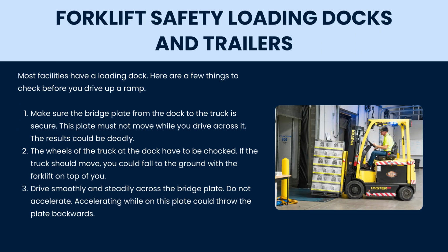Before driving up a ramp at a loading dock, check that the bridge plate between the dock and the truck is secure and will not move while crossing. Also make sure the truck wheels are chocked so the vehicle cannot roll away. Drive smoothly and steadily across the bridge plate without accelerating, since sudden movement can dislodge the plate and cause a deadly accident.